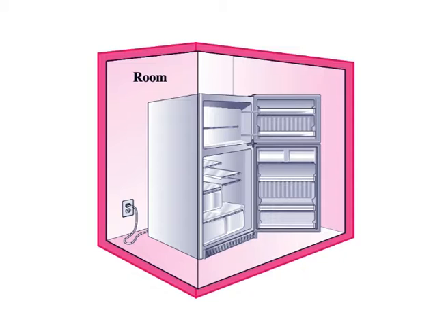The refrigerator or its motor does not store this energy. Therefore, this energy must now be in the room air and it will manifest itself as a rise in the air temperature. Therefore, we found that energy is conserved during the process of operating the refrigerator placed in a room. The electrical energy is converted into an equivalent amount of thermal energy stored in the room air.